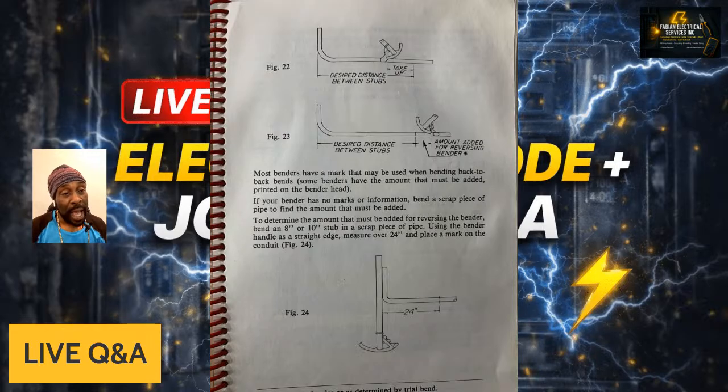So figure 22 is showing a back-to-back 90. Figure 23, same thing, is showing a back-to-back 90. The only difference is that in one of them, the measurements are a lot closer, inside of the pipe. The other measurement is almost like a stub 90 back to back. So it says most benders have a mark that may be used when bending back to back bends. Some benders have the amount that must be added printed on the bender head.